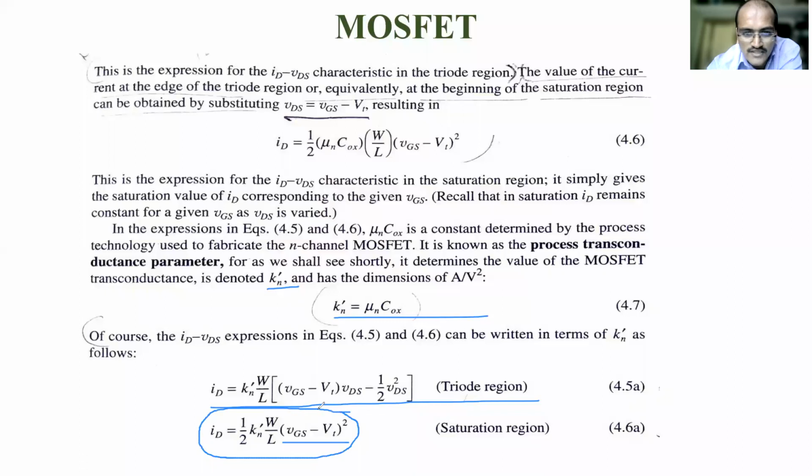To bring this discussion, I have done so much explanation. What is the device structure? What is MOSFET operation? What are its characteristics? And how do you get this equation? So now at least you know something. What is VGS minus VT? VT is the threshold voltage to make the MOSFET operate. VGS minus VT is the overdrive voltage, VOV. We'll denote it that way and use it in problems.